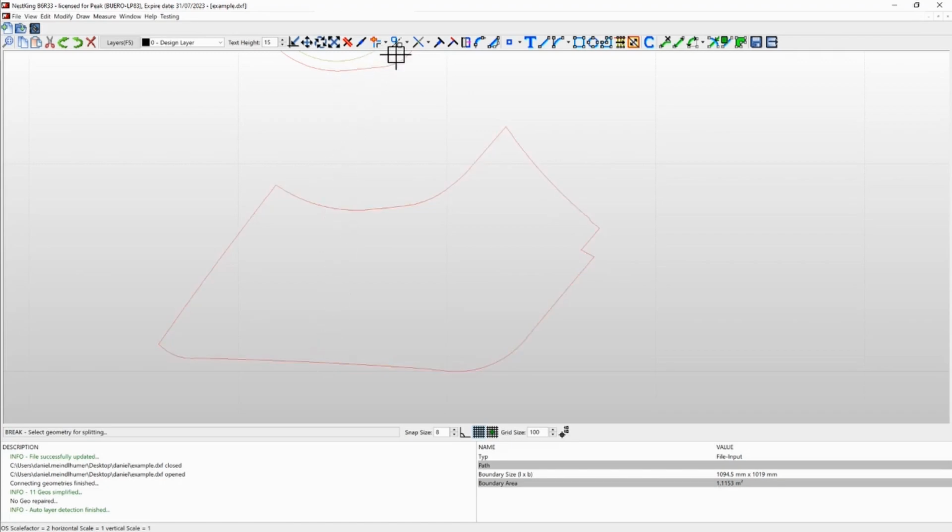Therefore, we choose the offset tool. On the one hand, we can use these buttons in the toolbar like this. Just click, for example, offset using round edges and offset values. Or otherwise, we can also use key shortcuts. So when I'm clicking the O key on the keyboard, the software already suggests offset, and then we just have to click enter or space, doesn't matter, and the tool is also active now.